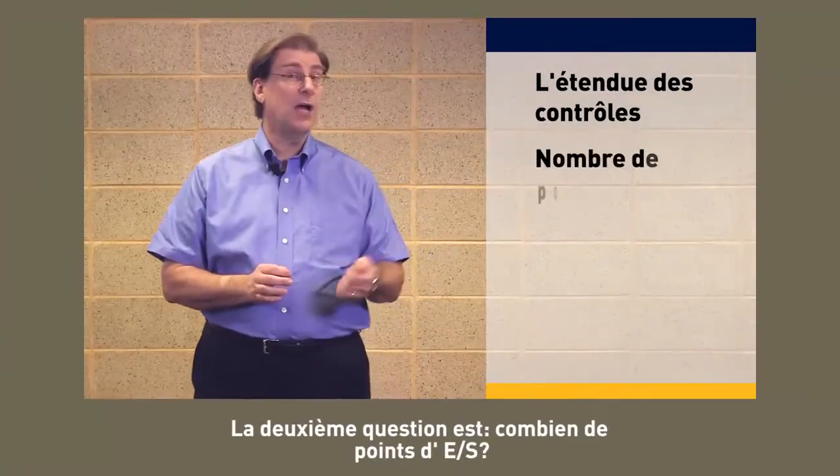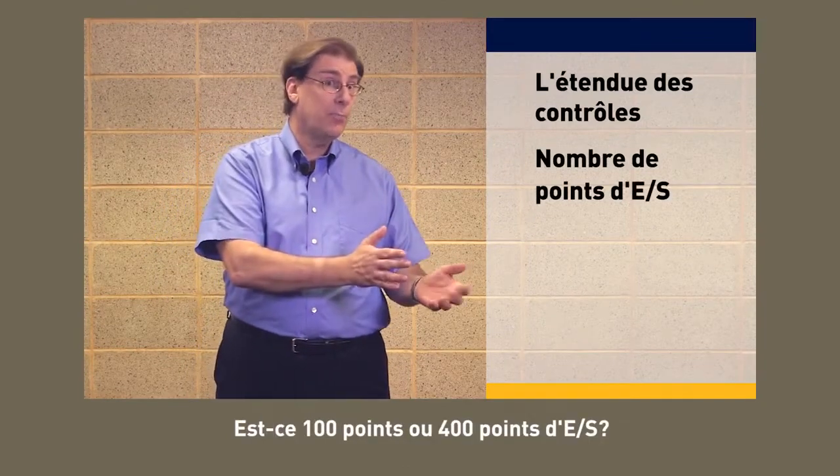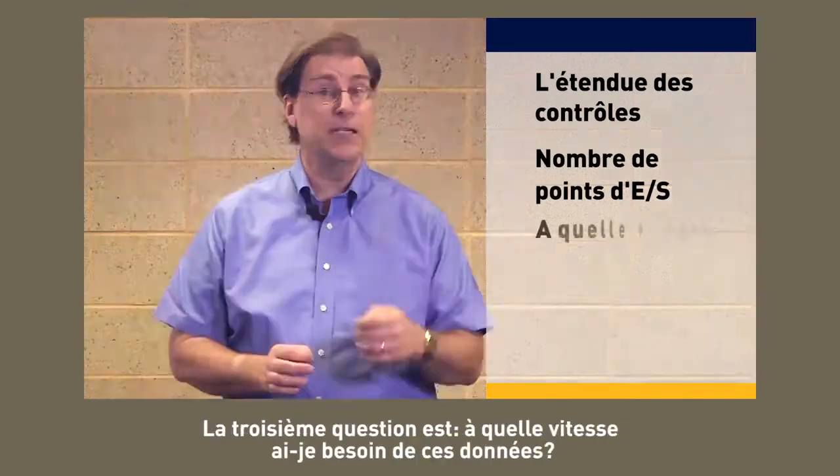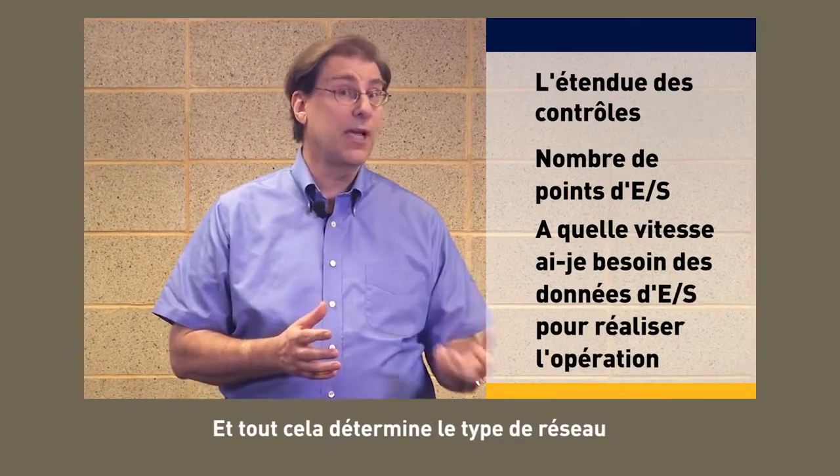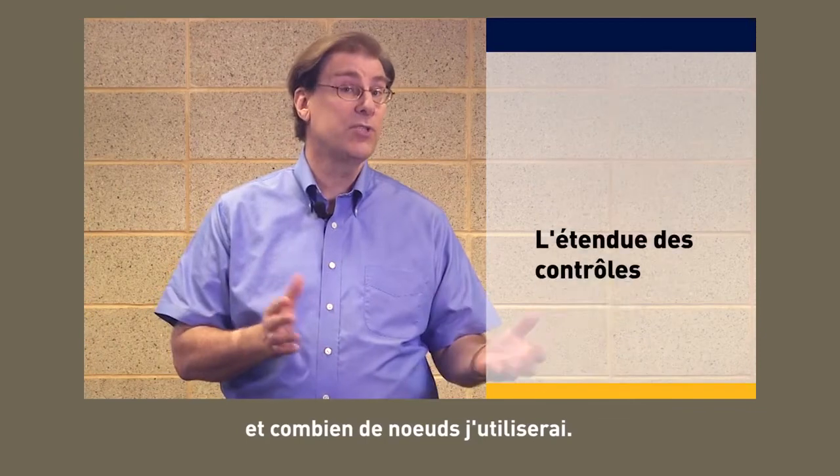How much control do I really need? The second thing is how many I/O points. Is it 100 I/O points or 400 I/O points? Number 3 is how fast do I need the data? So that determines the type of network and how many nodes I'd be using.